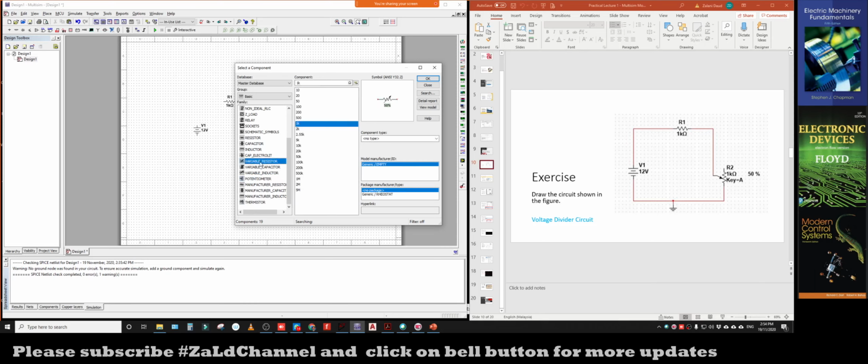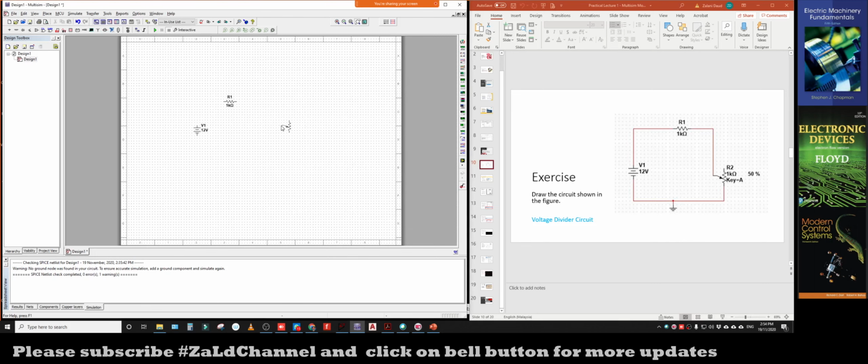So we have the variable resistor as well, but we are not going to place this one because, as you can see in this figure, this is actually the potentiometer. But actually, a potentiometer can function like a variable resistor. I will explain it later. All right. So basically, we place this component, the potentiometer. If you would like to rotate this component, by default it will be like this. If you would like to rotate, just press Control R, and the component will rotate about 90 degrees. Once you finish rotating, just place it somewhere on your canvas.